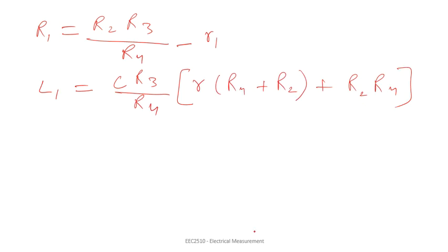So just by looking at these balance equations you can see that, to obtain easy convergence of balance, the alternate arrangements of this R1 and this small r should be done, as each appears in only one of the two balance equations. That means if you change R1, only this parameter will be affected, as R1 is not present in this equation. Similarly for small r: if you vary it to obtain balance, it will only affect the inductance, not this value.